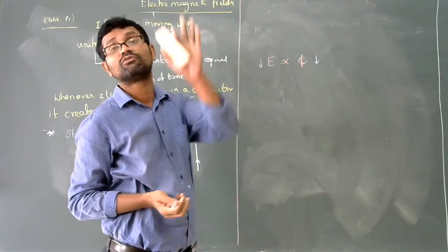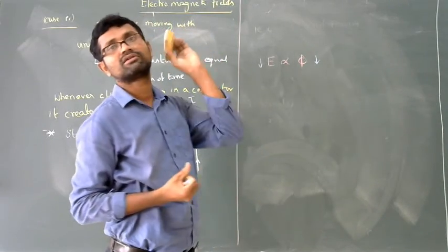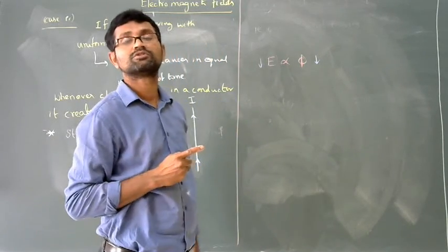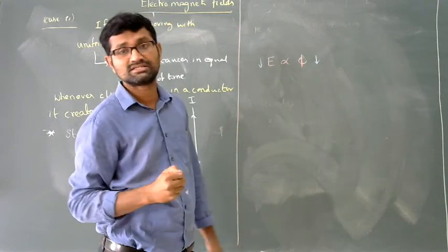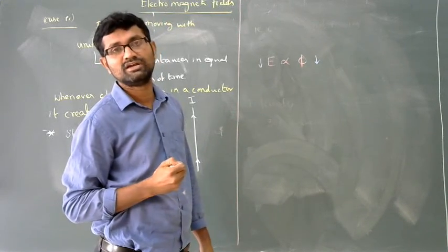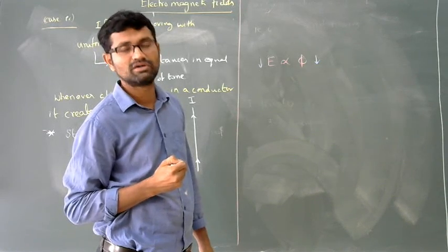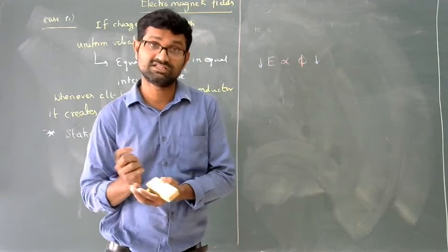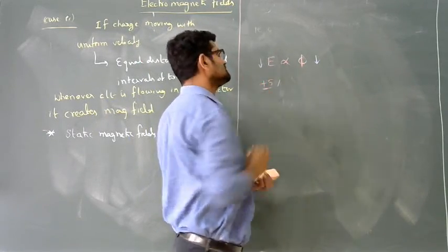But you designed all the loads to work for constant voltage. That's why we have to generate and transfer the constant voltage that the loads require. Based on that, some standards are specified. Government specified standards: in India, single phase consumers need a 230 volts, 50 Hz voltage source. Plus or minus 5% tolerance is adjustable. So that's the constant voltage.